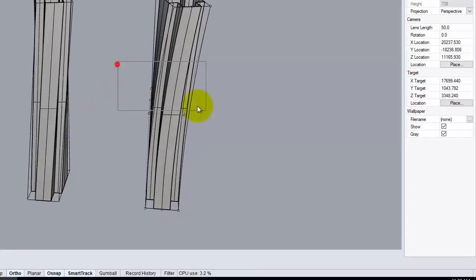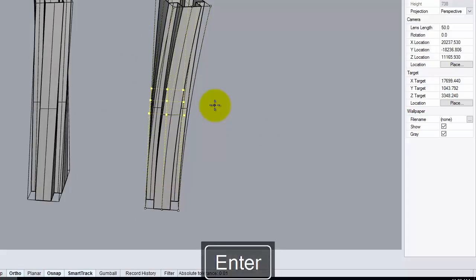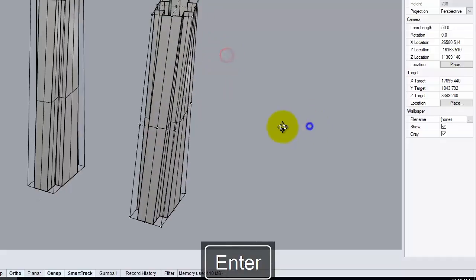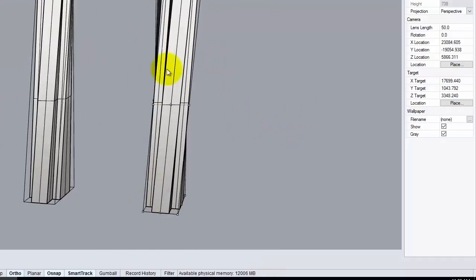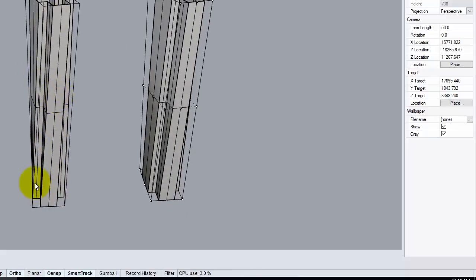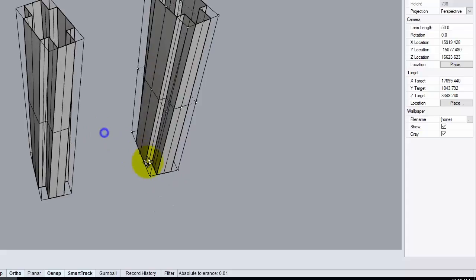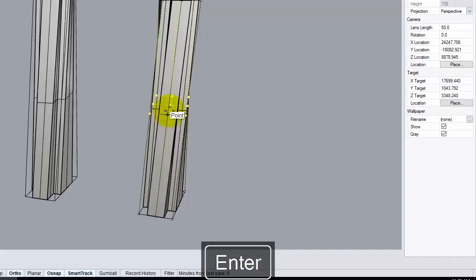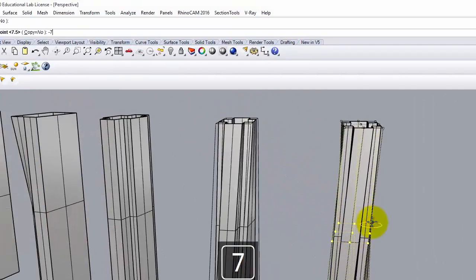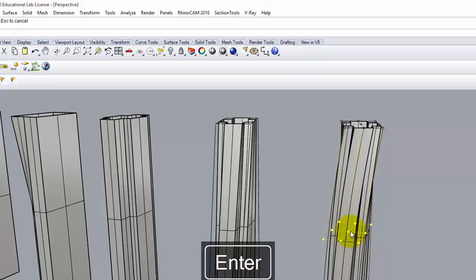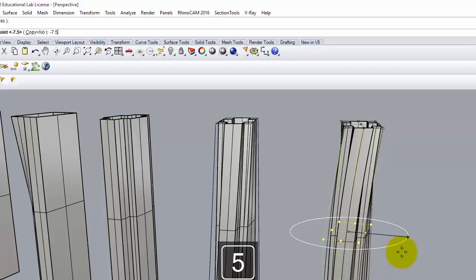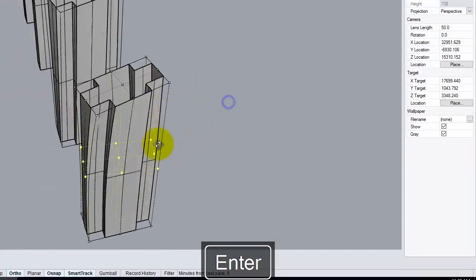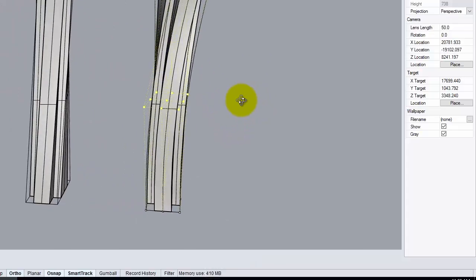Okay? We could smooth it out a bit by rotating this back by 7.5. Right? And it's going to smooth out a bit, but it's still a bit of an arc compared to our perfectly straight line. Okay? But I can also control this. Remember, I can work with just this middle section. And let's go back. I went back to negative 7.5, and I could rotate this whole thing from the middle by negative 7.5. Right? And I can really start to tweak what's happening in this particular shape.